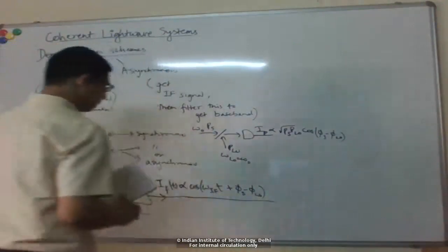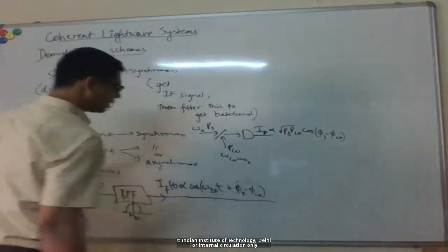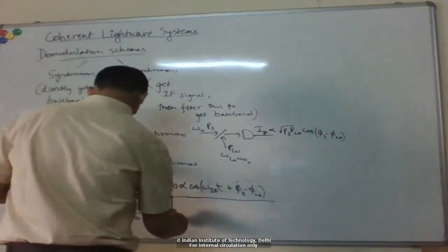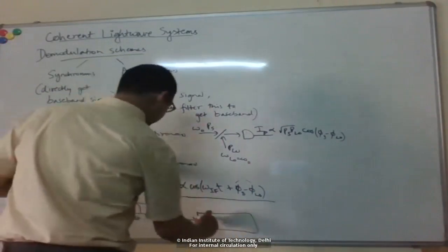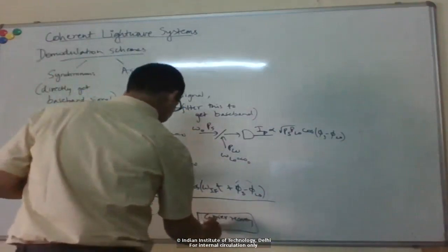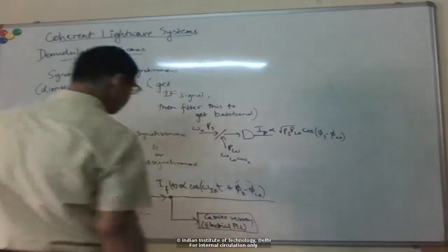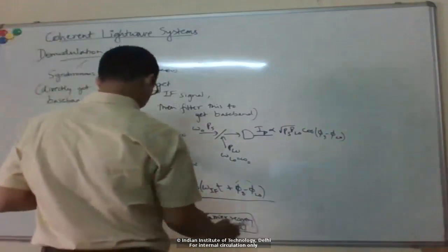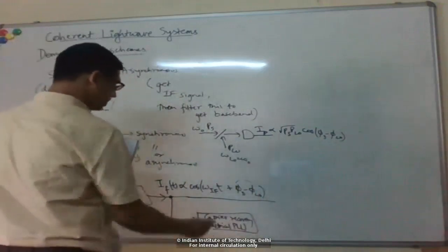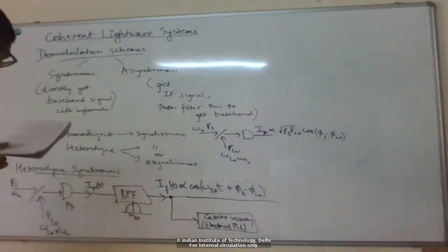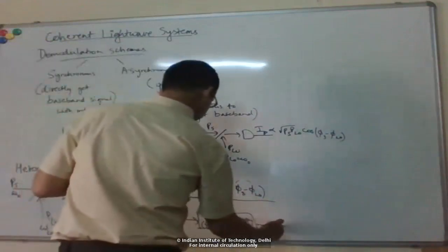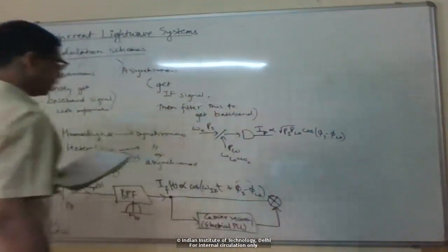Then let's say I'm doing phase shift keying and I want to recover the information in the phase. So what you do is carrier recovery. This is some electrical phase lock loop circuit, PLL. You might have heard of circuits like the Costas loop or squaring loop. Some electrical PLL circuit does carrier recovery; basically it recovers this frequency omega IF and also locks the phase.